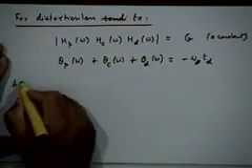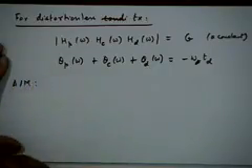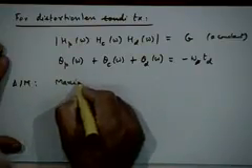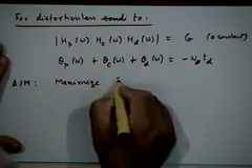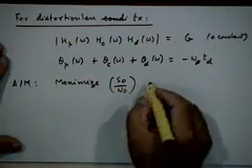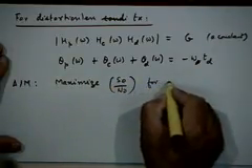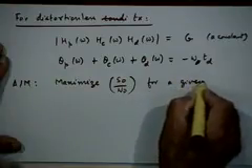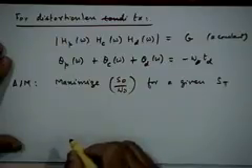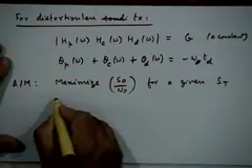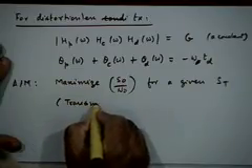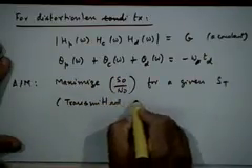So if you were to formulate the problem mathematically, this is what we want to do: maximize output SNR, S_0 by N_0, for a given transmitted signal power, for a given S_t, right. S_t is your transmitted signal power or received signal power.